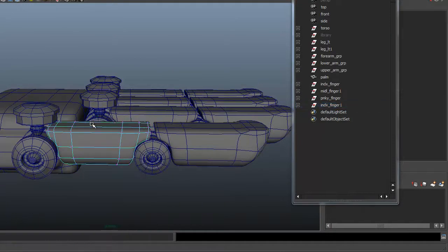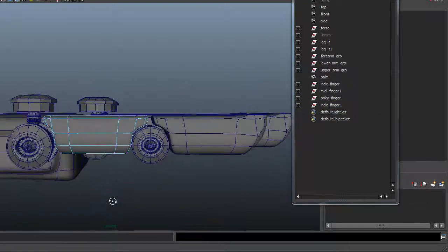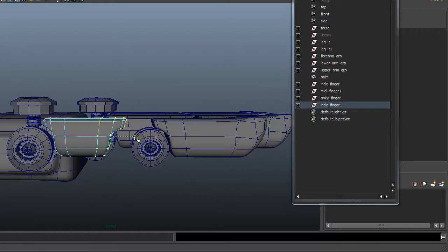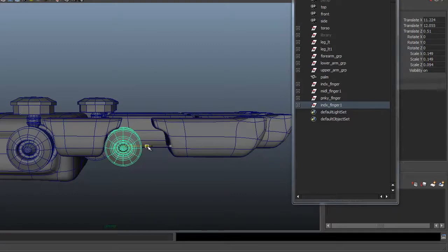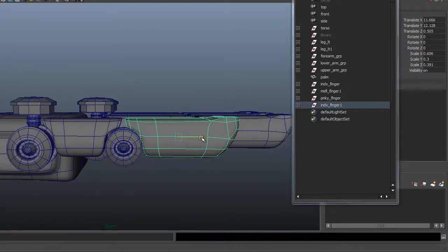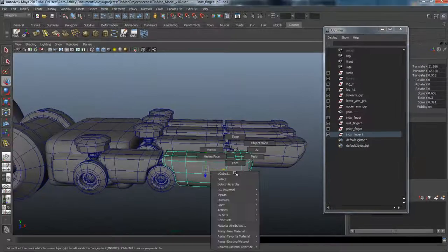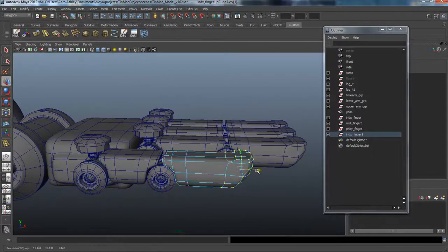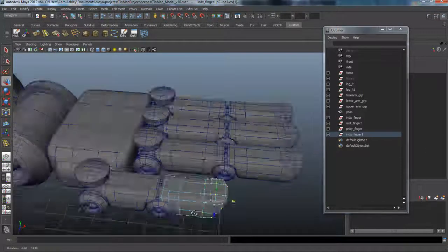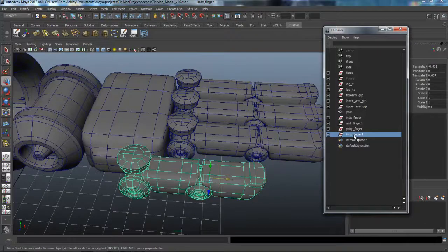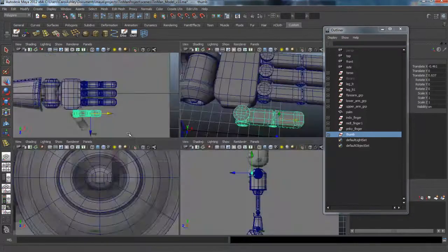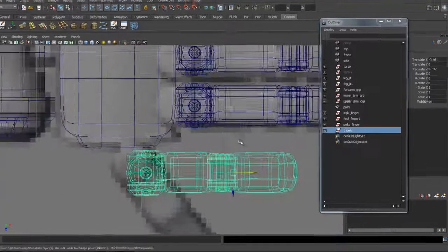So I'm going to select the vertices on this first section and just grab the whole group on one end, shorten that down, grab this joint, push it down there, bring this down, get that into position, and grab the vertices on the end here with the marquee and shorten that down as well. Let's come out here in the outliner and rename it Thumb. And we can move the pivot point now. Let's do that from the top view.